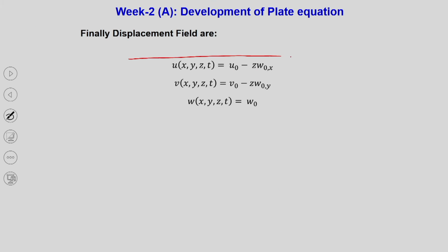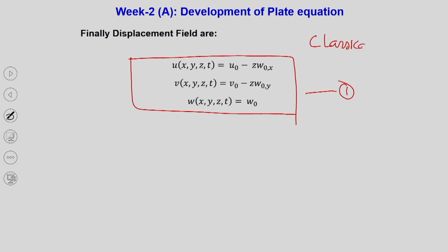So, finally, we have this assumed displacement field. Sometimes you may say assumed, sometimes you may derive it mathematically, but this mathematical derivation is only possible for the classical plate or shell case. If you are interested in first order or third order, then those kinds of things cannot be done.